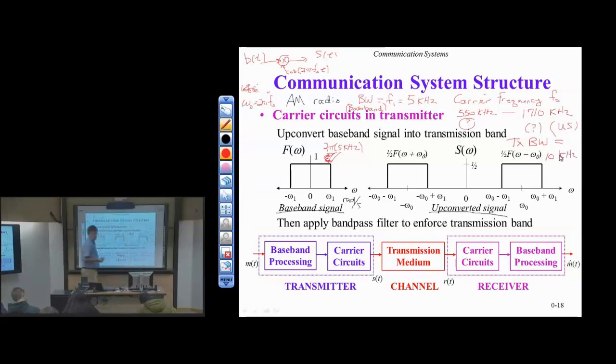and so your channel spacings in AM radio in the US are separated by 10 kilohertz. So you have 550, 560, 570, etc. So if you look at a radio station, they're not going to say tune in to 553. They're going to say tune in to 550 or, I don't know, does anyone still listen to The Zone for UT Sports every now and then? I don't know. Okay, so that's at what frequency? 1300 kilohertz or 1.3 megahertz. Not 1303 or 1298. It's at 1300 kilohertz.